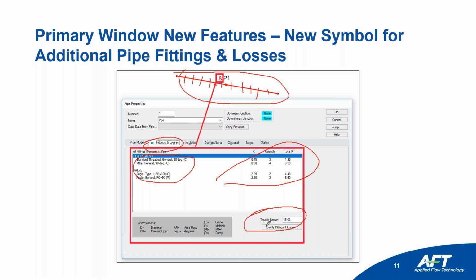And we march down that pipe and calculate what your pressures and temperatures and velocities and everything else are. So the moral of the story is, when we average out this K factor, maybe we've got a K factor of 2 averaged out along each axial point in the pipeline. If you have a K factor of 2 averaged out here, but your real fitting is 2.5 or whatever, your results are going to be a bit different.